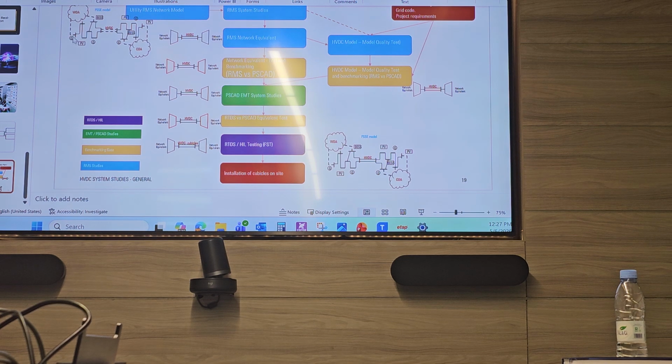If during these simulations they identify that the system will become unstable, for example, they will ask how to make it stable. They may say, besides building this in order to energize this HVDC in the future, let's say in 2027, in this planning the system will be unstable, but if we build one more line between this substation and somewhere else, the system will be stable.